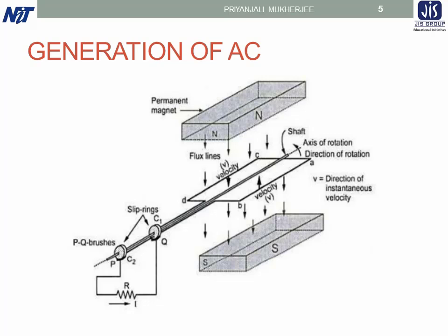The AC induction motor is much cheaper in initial cost and maintenance, because it has no commutator, and it is more efficient than a DC motor for constant speed work. So it is desirable to generate power as alternating current. The high transmission efficiency of AC makes the generation of electrical energy economical, by generating it in large quantity in a single station and distributing it over a large territory. The switchgear for an AC system is much simpler than that required for a DC system, and the maintenance cost of equipment is also much less in the case of AC.